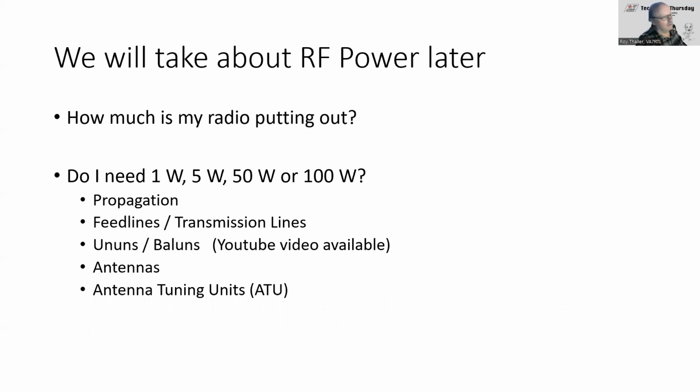And later on, we'll talk about RF power. How much power do you need coming out of your radio, and that's measured in watts. Typically your smaller radios are anywhere from 1 to 5 watts. Your handhelds might be 5 or 10 watts. And then when you get into your mobile radios, you're getting into 10, 20, 30 watts, up to 50 watts. And then when you're getting into base stations, it's 100 watts sort of minimum.